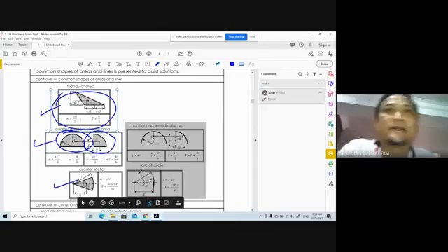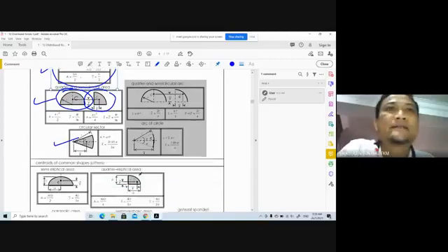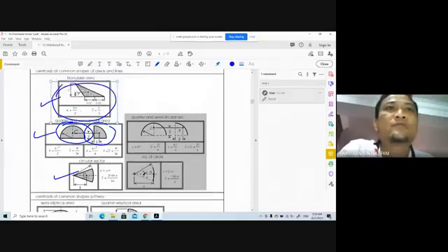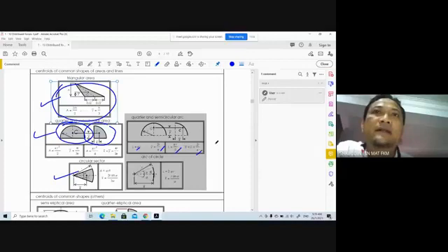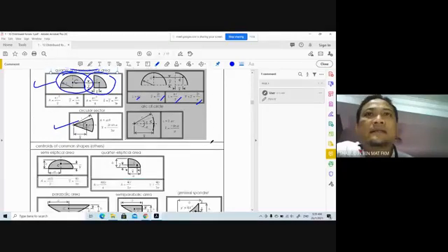Okay, in case you are given the lines, that is, not area. If the line is a semicircle, the length of the line is pi r, and y bar is 2r over pi. For a quarter circle, you will have L is pi r over 2, and x bar, all are given here.